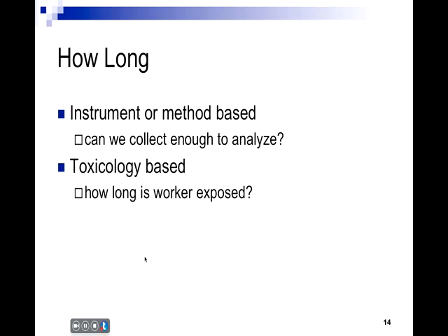How long? This is where you really need to develop a good relationship with an analytical laboratory, because they can tell you how much sample you need to collect in order for them to be able to analyze it. And so this could be very helpful in determining if you need to collect samples for 8 hours or 48 hours, because sometimes if you don't collect a sufficient amount, the laboratory can't analyze it.